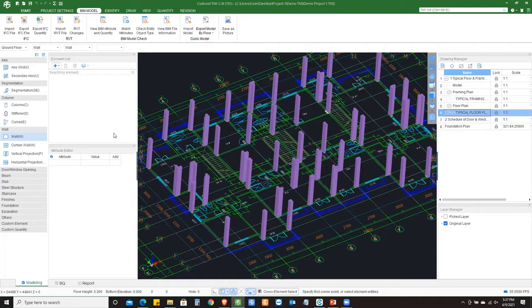Okay, so basically you can export it in IFC. Of course, there is no direct export to Revit because it's not Revit, but you can import a Revit model. If you export it in IFC, it actually contains all of this information. All this information gets into the details of, let's say, the type or the materials inside of your Revit. The family is a completely separate topic, but it retains all of that information, in other words.